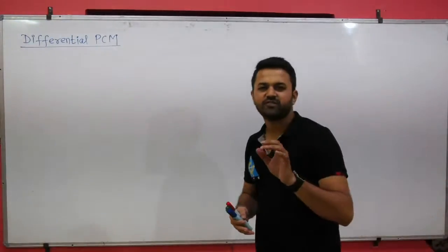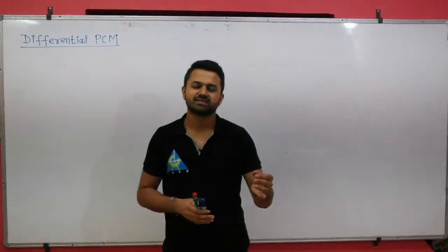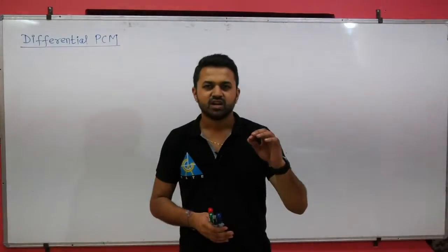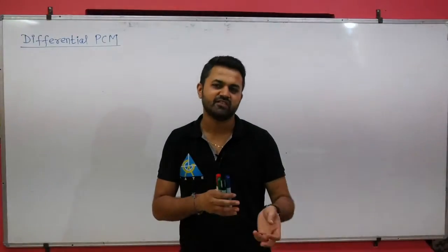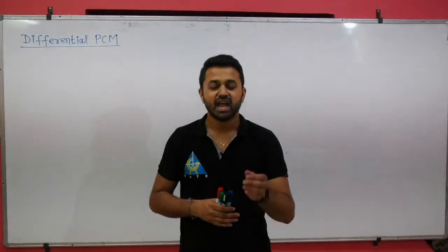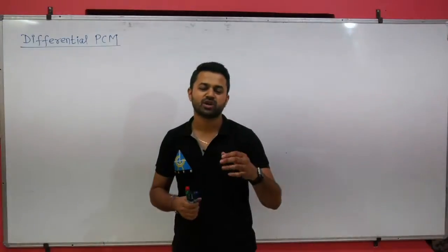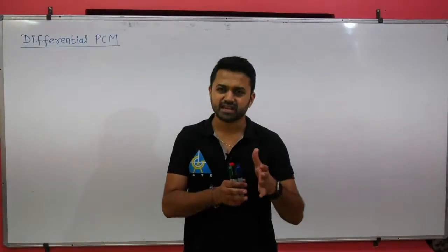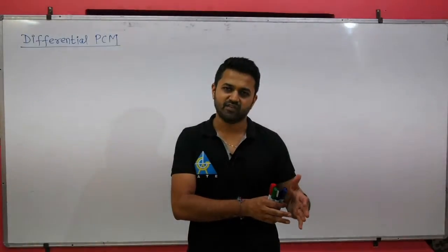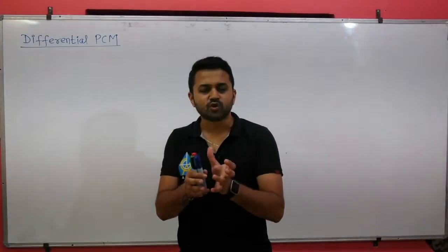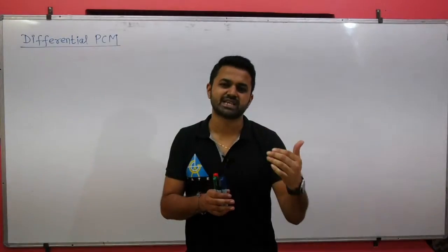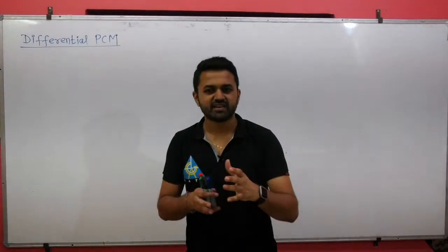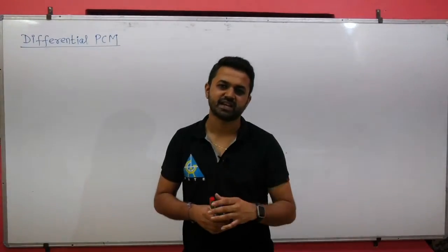Yes, we are only focusing on the step size because we have fixed the number of quantization levels. To increase the number of quantization levels we have to increase the number of bits, and if you increase the number of bits your bandwidth also increases. So that is why we are not increasing the number of bits or quantization levels. We keep that value constant and try to reduce the step size by reducing the peak value of the signal. We can reduce the peak value of the signal by taking the difference between the samples.